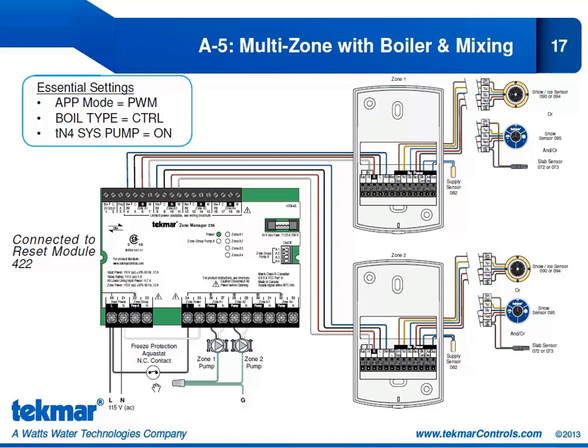The freeze protection aquastat is wired in line with this jumper. It is a normally closed contact, so normally you will have power at Zone 1 and Zone 2, and they will operate whenever those heat relays close for each 654. However, if we do approach temperatures that are near freezing, this normally closed contact will open and we will not be able to operate the Zone 1 and the Zone 2 pumps. There won't be any power there.